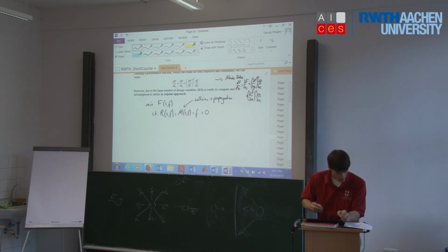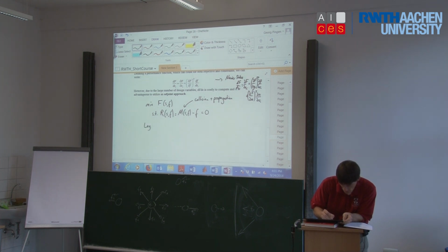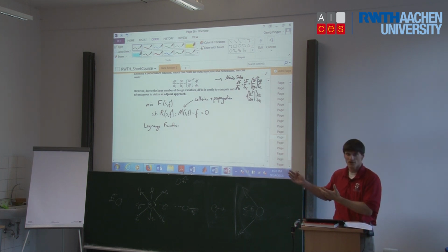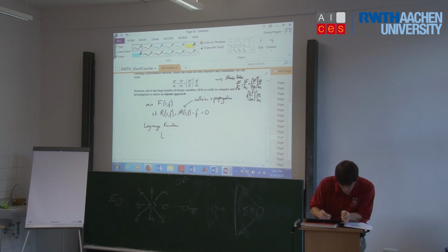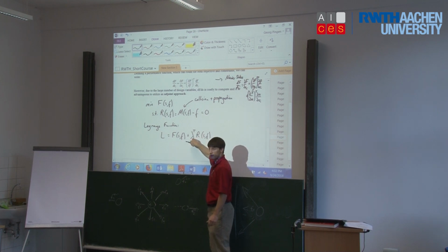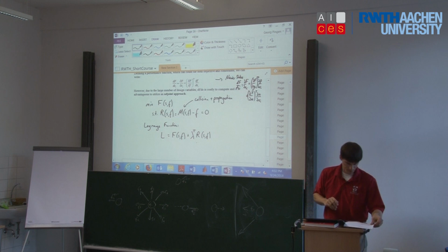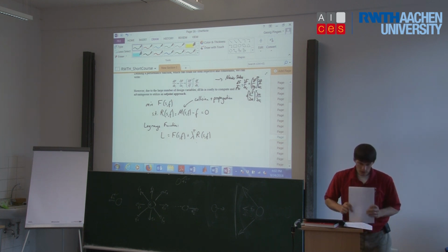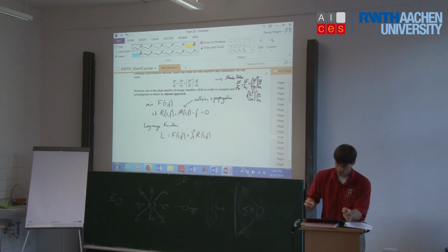So if we have this problem, we can now again write a Lagrange function. That's basically what you probably do when you do your mesh optimization of some sorts. So you write a Lagrange function L(s, f, lambda), which is f(s, f) plus your Lagrange variables, or your adjoint variables, lambda transpose times R(s, f). Now we apply this residual as kind of a penalty, so we write a new Lagrange function for our Lattice-Boltzmann algorithm. We can write KKT conditions.